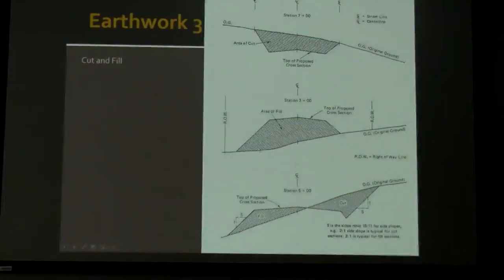Here again we have a fill. We have a fill project where we'll be filling it to get a nice roadway profile up above the slope of the ground. And all this would be to have a continuous and uniform grade for our pavement. Here we see the cross slopes for the two pavements, as well as the ditch or the runoff slopes, which are much greater.